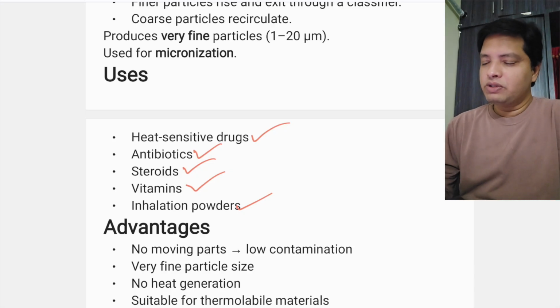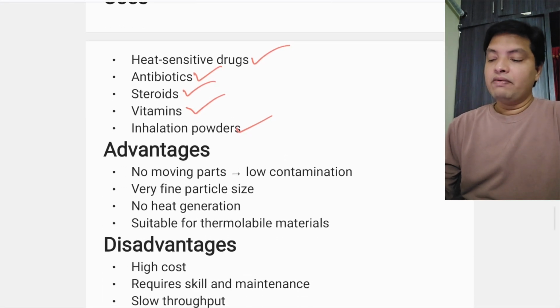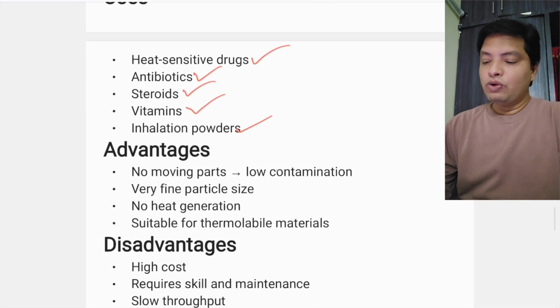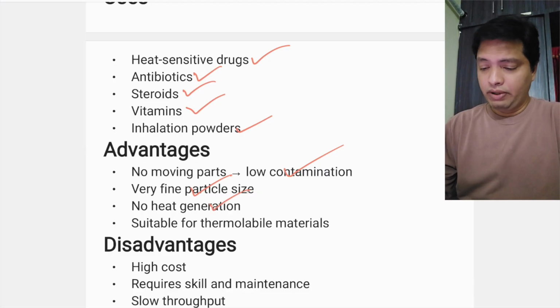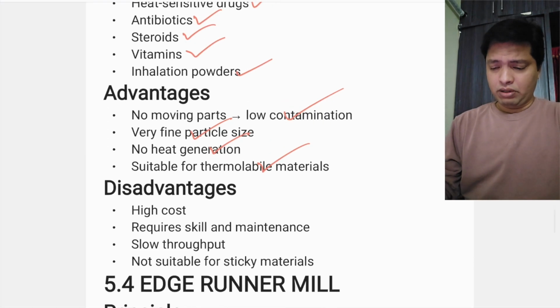So this can be used for size reduction in the fluid energy mill. No moving parts, obviously there is no contamination. Very fine particle size will be achieved. No heat generation, suitable for thermolabile drugs.